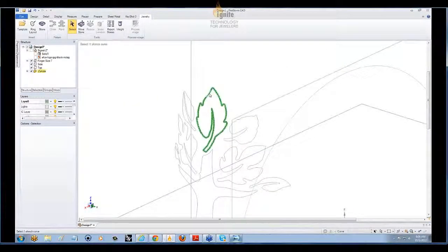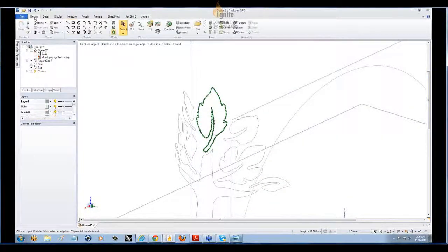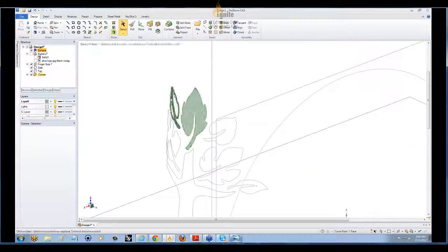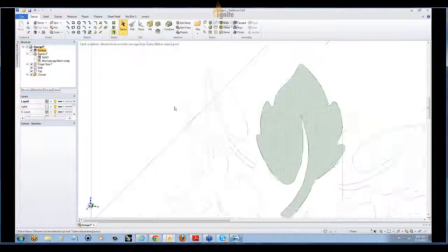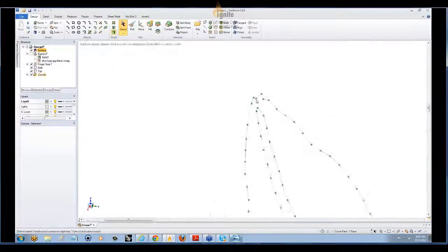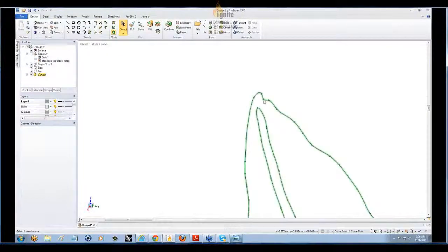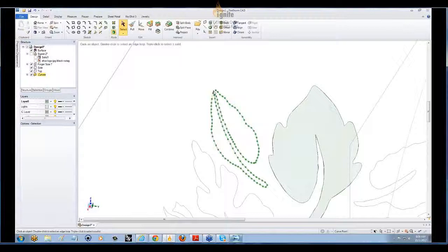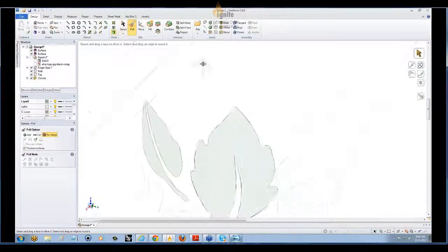You can either project the curve onto the surface, or you can grab the line, go to the Design tab and fill it. Now this is our curve as a surface, and you can pull this. The same thing works in any formatted file in here. Let's say I don't like these corner points. I can delete the point to have something nicer in here, and you can fix the curves. I can always grab the curve again and fill it. Now I can pull this